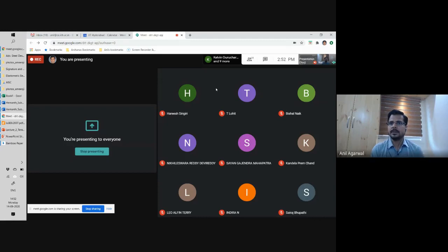It could be yielding of the metal. And then when we say yielding, we don't always restrict yielding. So there would be a limit to the yielding that we allow. Yielding, it could be rupture, it could be buckling, those kind of things, bearing failure, shearing rupture, shearing deformations.